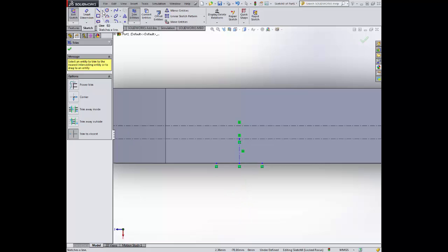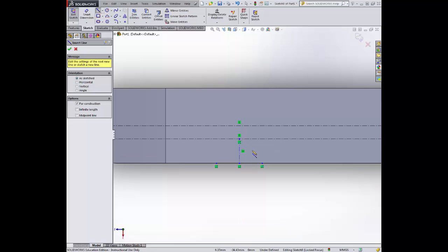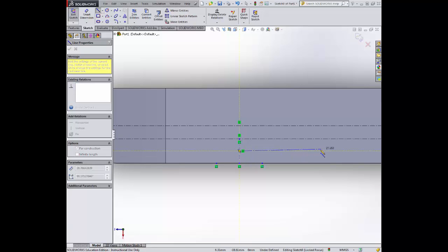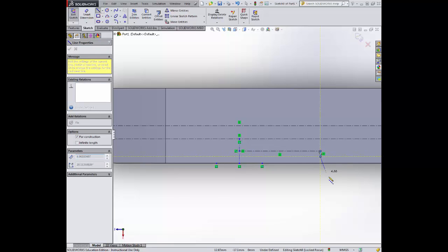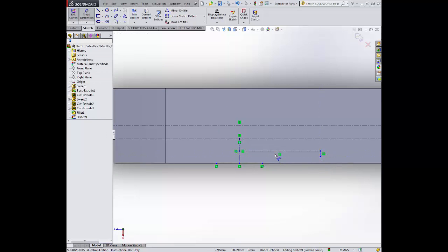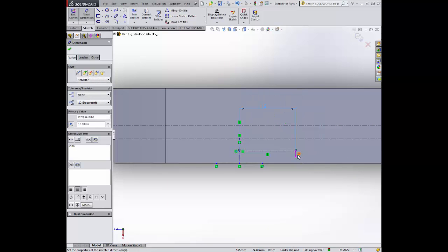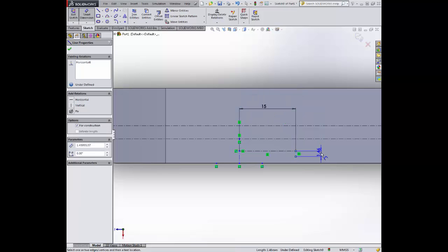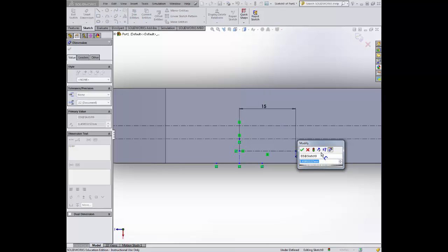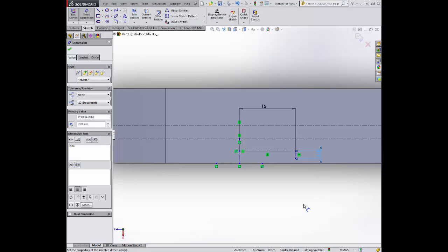As I said, for a lot of this I'm using center point, so you'll see that happen in a moment. So find the center point here, I'm going to drag to the right. Notice the yellow square with the black line through it says that it's straight. This is then 15, and the other line I've drawn here needs to be quite precise too. So 2.01 on that one.